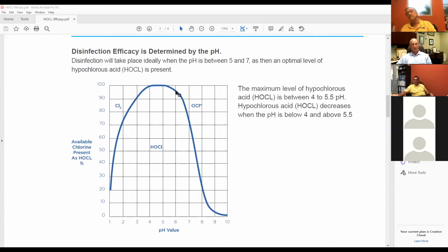It's why we start at 6, which gives us about 95 to 97%. And then as the solution sits in that tank, pH slowly but surely drops off. And our goal is to make sure that we don't get down below about 4.8, 4.7, which is giving us a hypochlorous acid of 100%, but no gassing effect. And so that's the key. And so by keeping it in that 6 range, for us, it's very important.